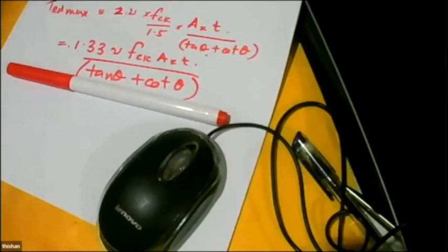Now, generally, when you analyze the structure as 3D, you don't get torsion. Because torsional moments are so small, we ignore them. That's a compatibility torsion situation. But torsion comes only in this very special situation, that is the transfer plate. No other place. So when you are having secondary beams, all those things, you don't have to worry about torsion.